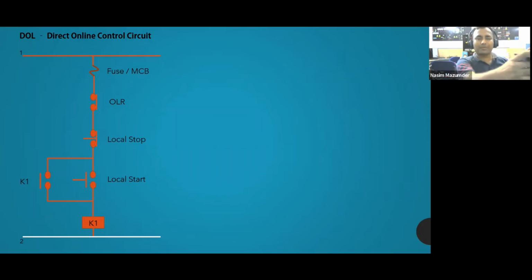Okay, so this gives me the full information, and I can even add the node numbers. If this is one, so this will be one. One ferrule will be connected at this terminal as one, and one ferrule at this terminal as one. Then, since we have already given number two to the neutral, you can use three for this node. This particular node is 3.